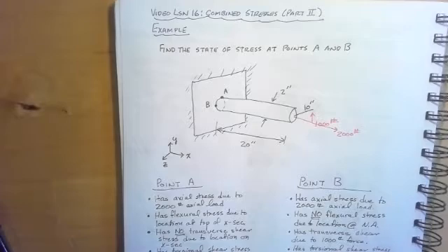You would have some axial force as the helicopter's shaft is going to suspend the cab. You would also have the potential for flexure and transverse shear as a result of lift forces on the blade of the helicopter.